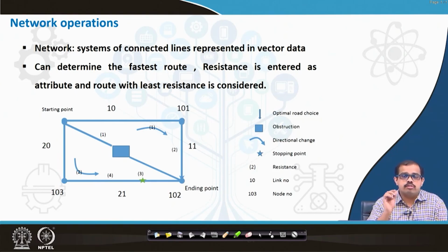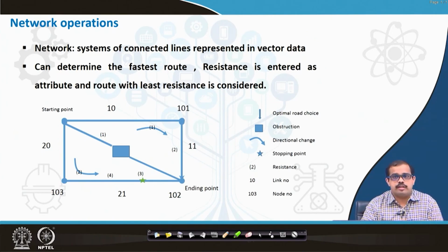Now I have to look at which wire may have been damaged because of its age or different issues that may occur. So, what I try to do is find out how these lines are connected, where they are connected, if there are obstructions in that region, what the loading conditions in those particular lines are, and what the amount of load is.